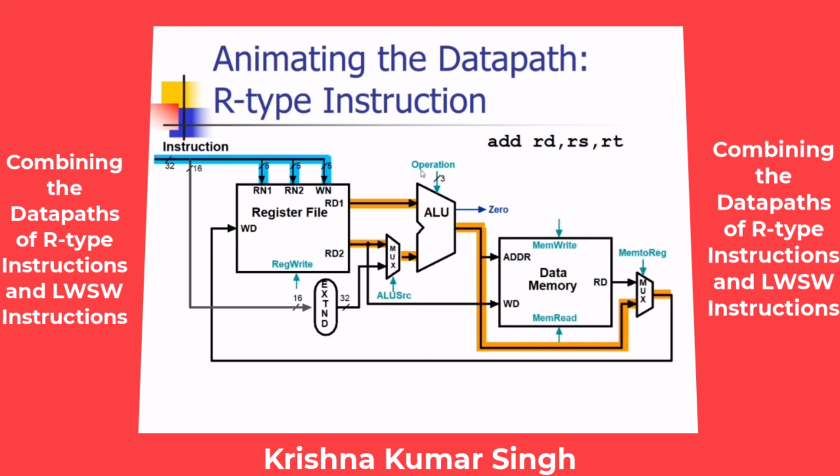Then these two data values will be computed, and according to the operation of the R-type instruction, one of the mathematical or logical operations will be performed over them, and the result will be given to the second multiplexer. So the second multiplexer should select this input. Therefore the signal MemtoReg should be 1.